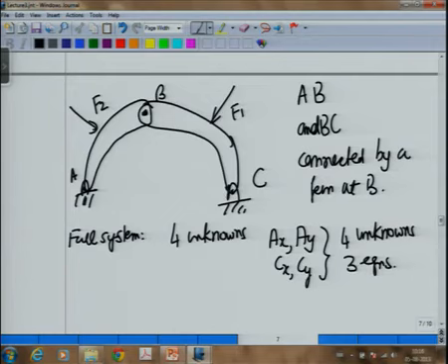See, if you are drawing the free body diagram only of AB, then forces at B will also come into picture. The link BC is exerting some force on the link AB, so that force will come. If you look at that force, then what will happen? You have a force at B, a force at A and F2. So, force at A will not be towards AB. Okay, let me solve it. I think that is the key to the solution.